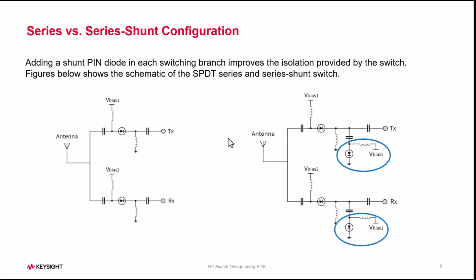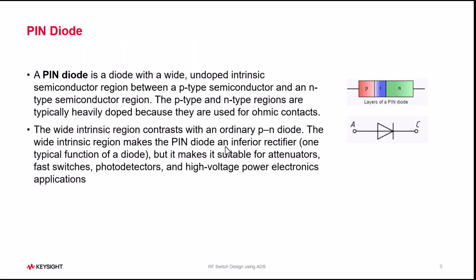Hopefully this explanation was simple enough for you to understand how the switch is working. Now if you need even more isolation compared to what can be offered by one shunt diode, you can think of putting in another shunt diode by keeping the return loss and impedance matching requirement in mind. However, you are free to play with the topology depending on your isolation requirements.